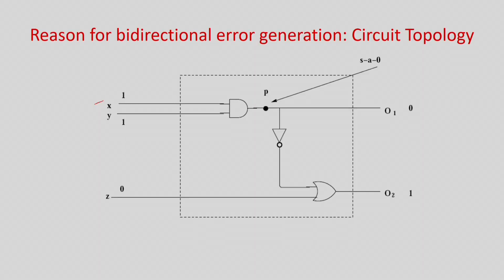People found out why bidirectional errors are there, and then they tried to avoid it by one means: just do not have any logic sharing between the outputs. People have written a lot of papers in this direction, that you make parity groups and so forth. You can read on this. That is future research, a lot of work is still going on: instead of entirely separating the outputs, having no logic commonalities between them, can we make groups? Then we can solve it as a graph coloring problem, and there are n number of papers on this. But the idea is minimum logic sharing between the outputs. If there is no logic sharing, no fault can lead to multiple bit errors, and it will be very easy, but that will make the circuit very large. As a trade-off, people try to see if some groups can be made, etc. Those literature you can read.